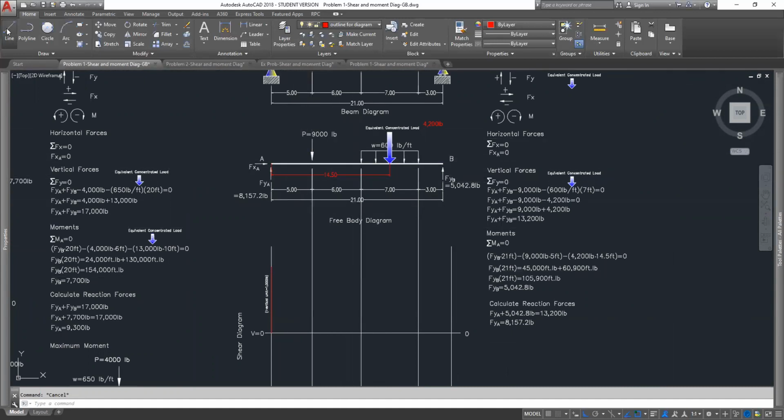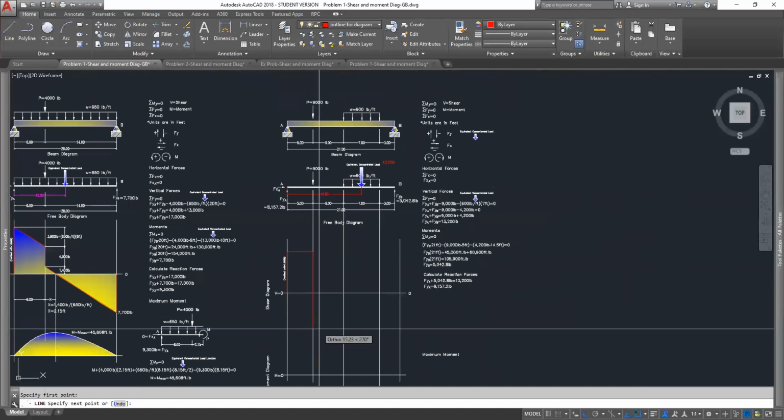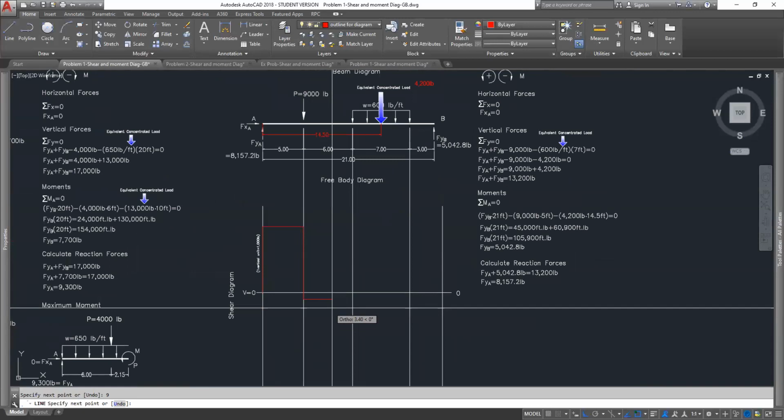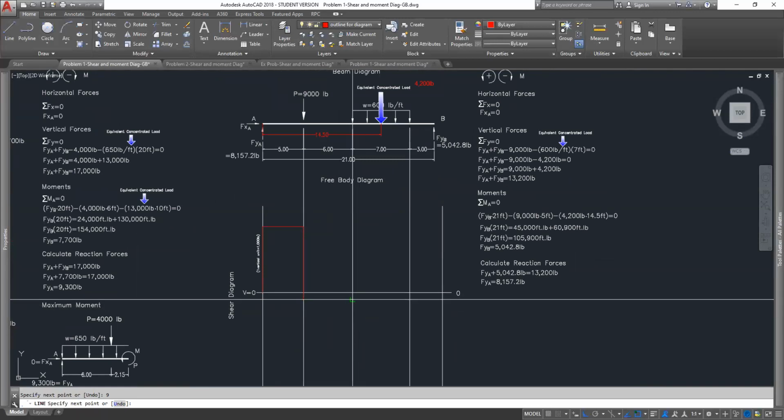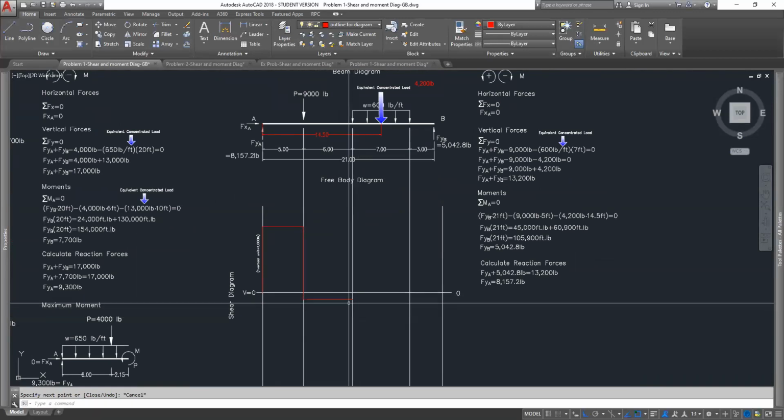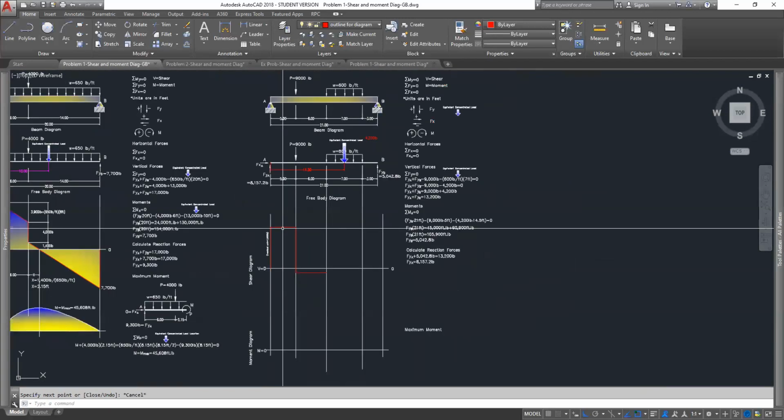So what ends up happening is that our shear diagram is shown as a horizontal line right here until we have our next event, which is a negative force, the 9,000 pounds, because it's going in the down direction. And I'm going to go down 9, enter. And then I have nothing again happening until we begin our distributed load at this point. Everyone got that?